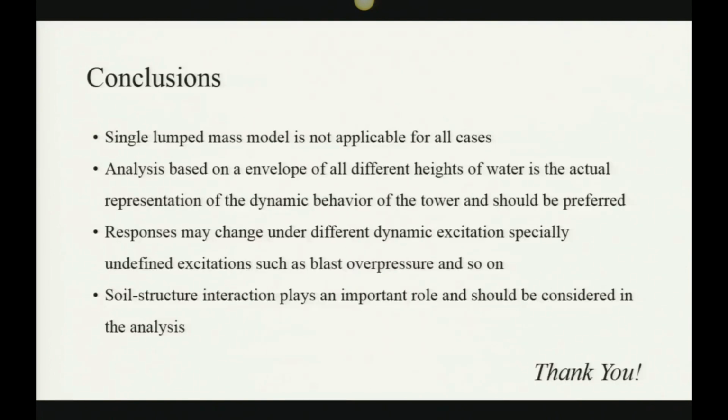So in conclusion, we can say that a single lumped mass model is not applicable for all cases, because the best behavior would be to consider different heights of water in the tank to analyze it, to be more representative. And what we did, the whole analysis is based on a free vibration. If we have a different excitation, like a blast overpressure, those results might change and we might have different behavior. And also the soil structure interaction plays a very important role.